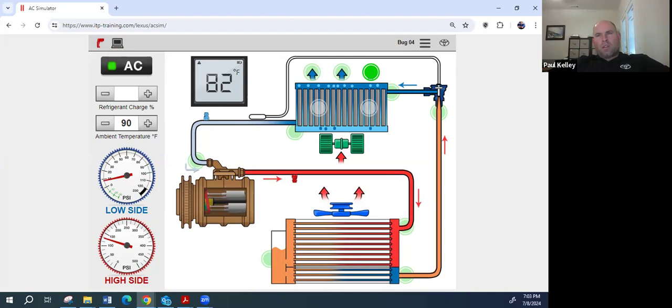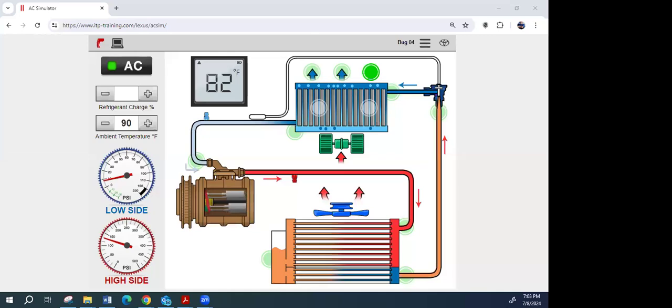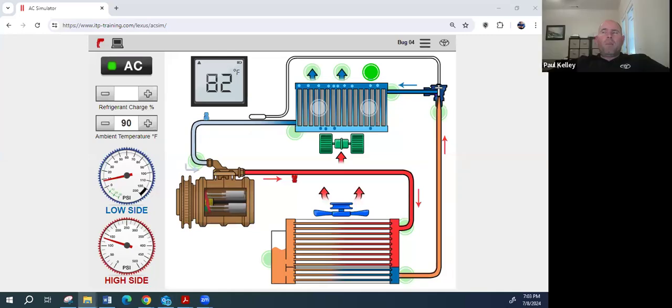All right. Anybody want to go ahead and, now that you're understanding what we're doing, go ahead and give me some advice on what we should check next? Expansion valve. Well, how are we going to check that? Like, what tests can we do? I want to do tests more so than replace parts. Oh, Renee says in the chat, the low side's too low. I agree. If we put the gauges on there, that low side being at a 9 or an 8, and that high side, well, that high side might look a little bit low too, but that low side is like really low. It's kind of interesting.